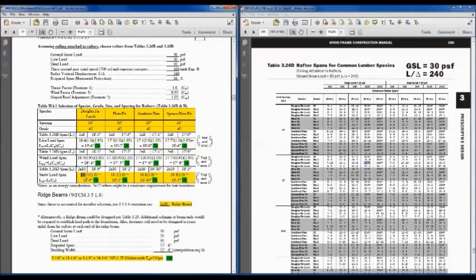And that's only able to be adjusted then by the thrust factor. For this particular case, for snow loads, you don't take the sloped roof adjustment factor. You don't take the wind load adjustment factor. So we've calculated our live load span, we've calculated our wind load span, and we've calculated our snow load span. And because this one requires a 2x10 instead of the 2x8, that's why this one controls the design.